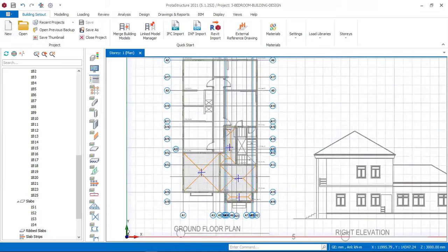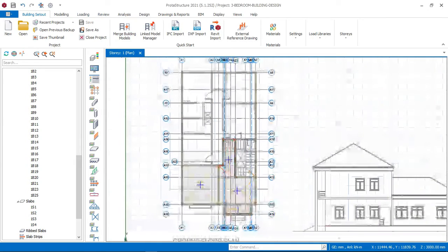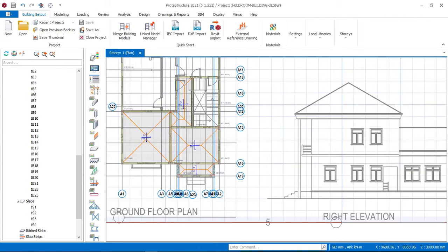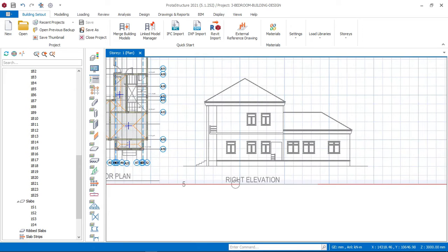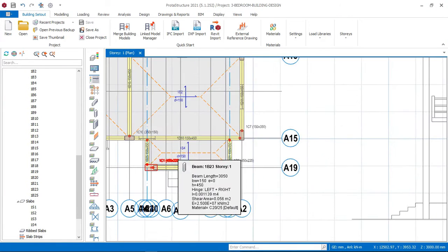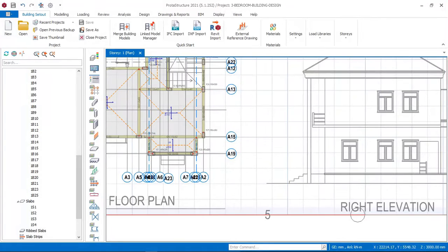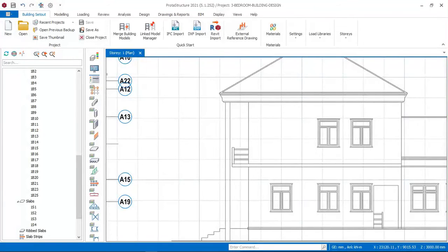Okay, so right now we are done saving. As you can see, we are done saving. So right now we will have to go and insert story, because all we have just created is this slab here, and now we will have to create this other story, which we will insert into this building, into this model here. And from inserting story, we will also see this cantilever here, which we have already provided for. So right now we will move on to what we have for today, which is to begin to insert this story, and also change the depth of the roof beam that is here.